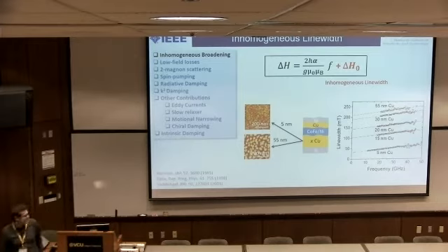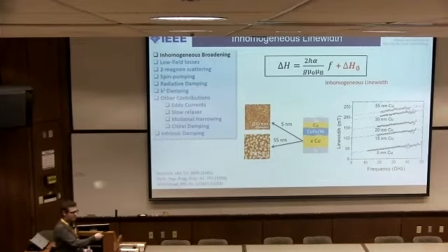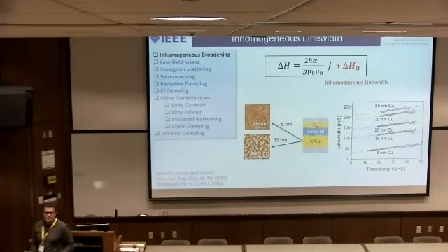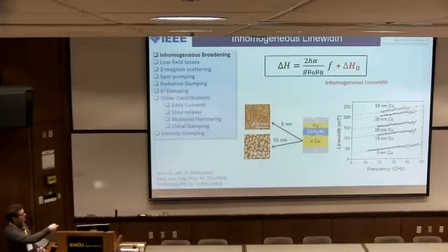And we can see this effect in the raw data. Here's an example. We take these cobalt iron nickel multilayers that we already talked about, and we grow them on a tantalum copper buffer layer shown here. Now, we happen to know that if we sputter copper onto tantalum, it grows rather rough. And so we can adjust that roughness by varying the thickness of this copper layer, so we can go from something that looks like this to a surface that looks like that.